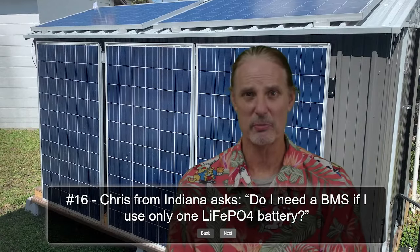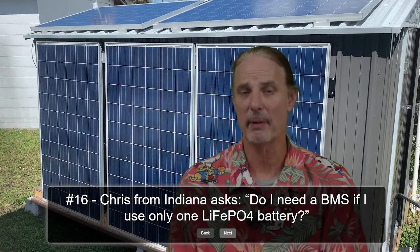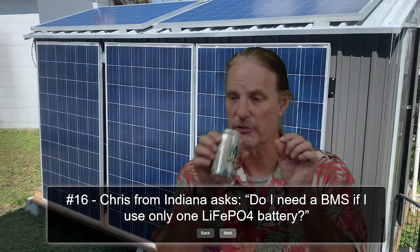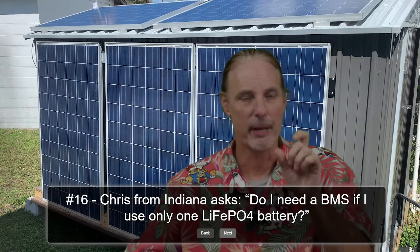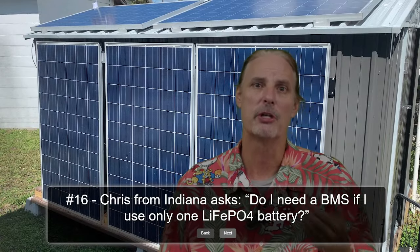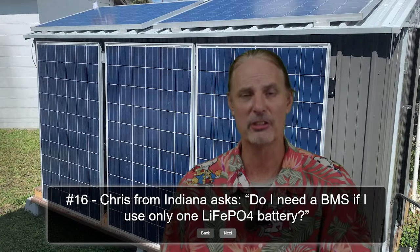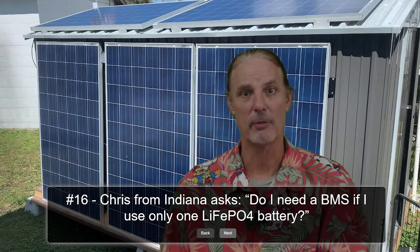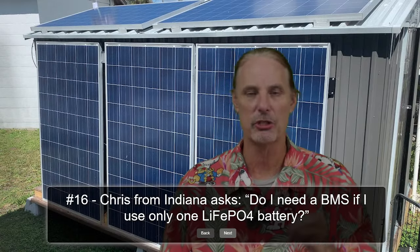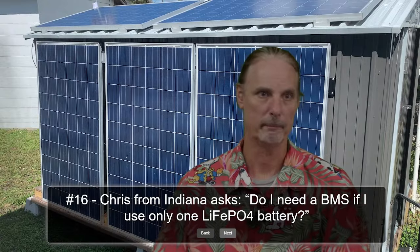You have a huge investment in these cells. The last thing you want to do is destroy one because you overcharge it from a simple mistake of not paying attention to the right voltages close enough. The BMS does that for you. It monitors each of the cells and makes sure that you don't overcharge them or undercharge them too much and cause damage to the battery. It also monitors input and output of the battery for maximum pull, maximum push, to keep you from damaging it in that way. In my mind, a BMS is an absolute 100% yes, you need one, and no, I wouldn't even consider thinking about using a battery without one.